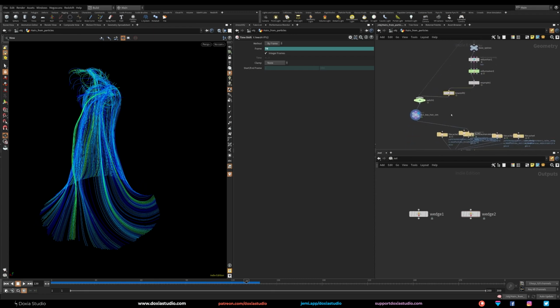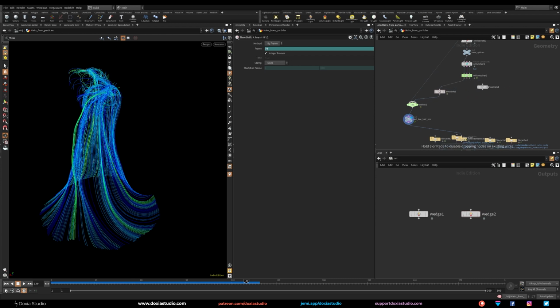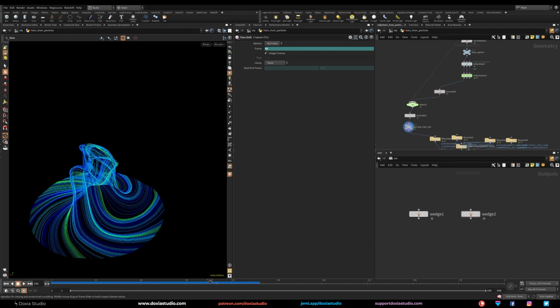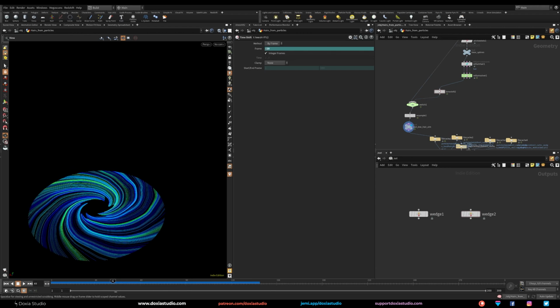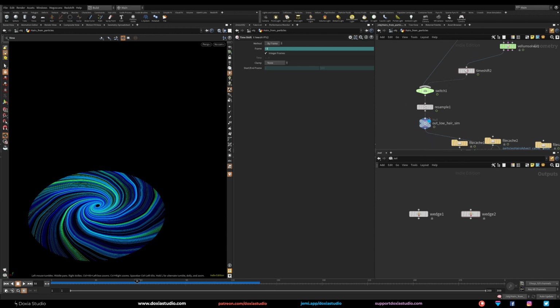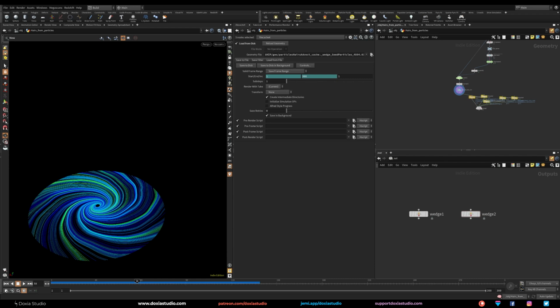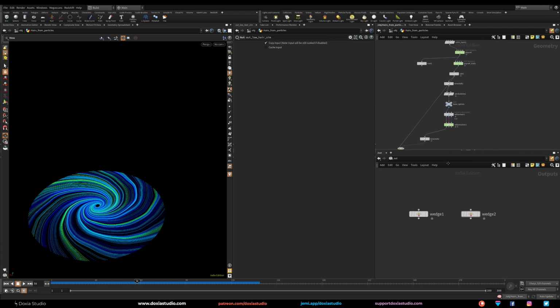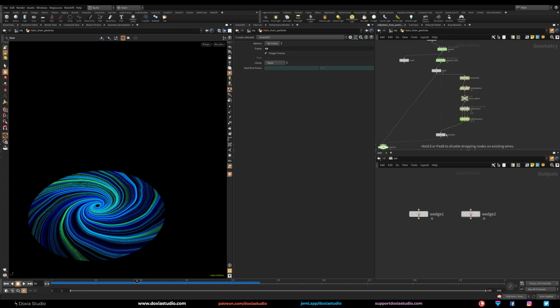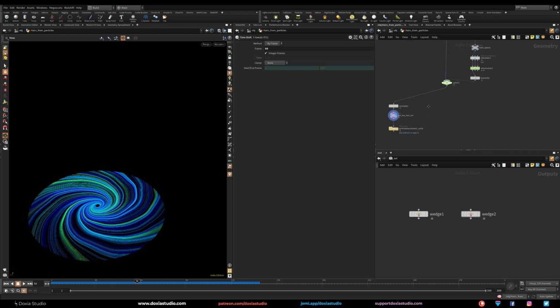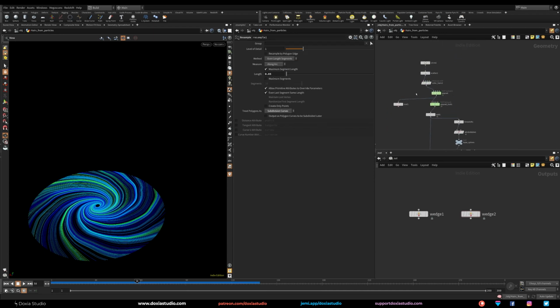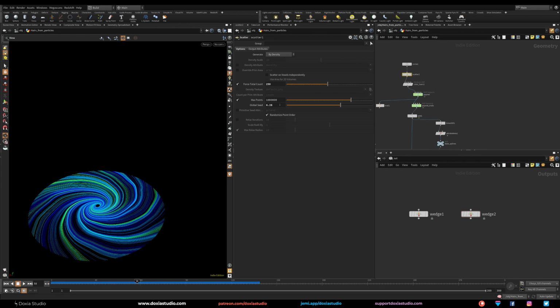And now we have all the animation, and I think that I want to resample after the animation. This will keep things more fluid and better. Okay, so the resample is after the switch. And now, oops, I have a few file caches wrongly here. I don't know why they are here. So now I have everything prepared for our wedge cache trick, to have it a little bit more dense. I already said that this trail won't work with our wedge. Okay, and now we are changing this global seed, and I think everything is correct.